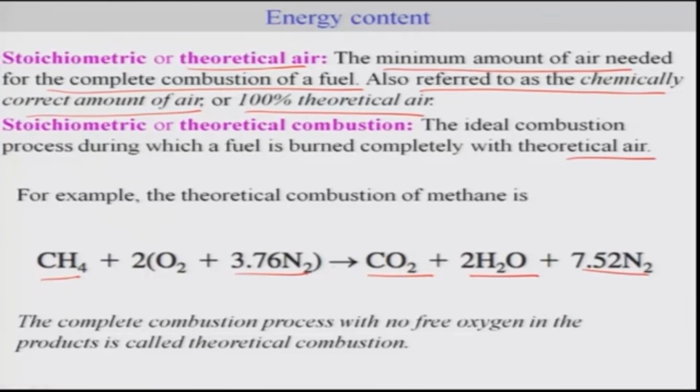So this is the complete combustion with no free oxygen in the product, and thus this is also a theoretical combustion. That means the theoretical air here is nothing but 2 into 4.76 kilomole of air. That is what you would call theoretical air. This becomes a kind of limit or criteria for which we can add additional amount of air in terms of excess, in order to have surety that the combustion will lead to completion.